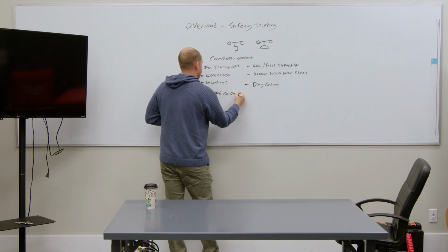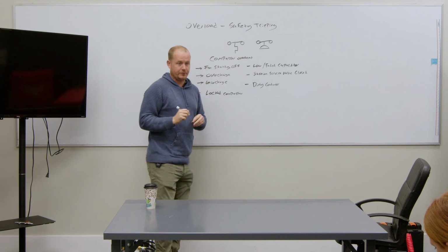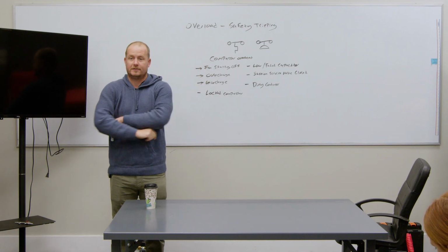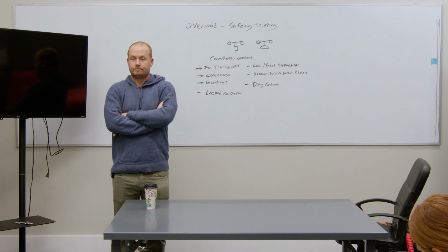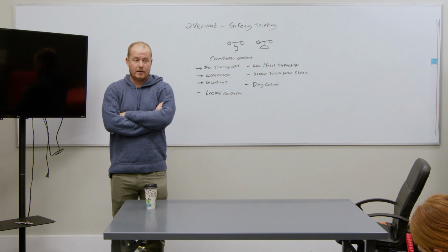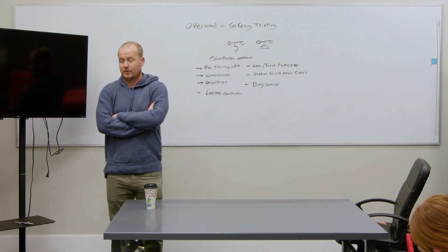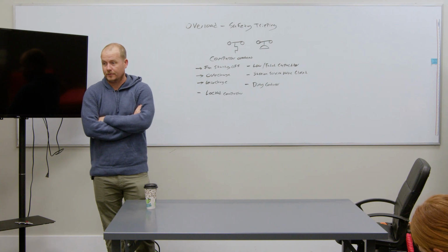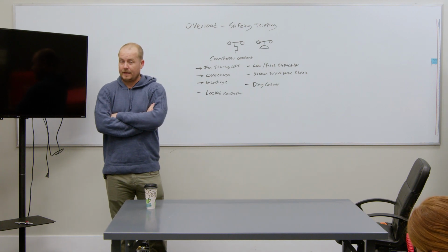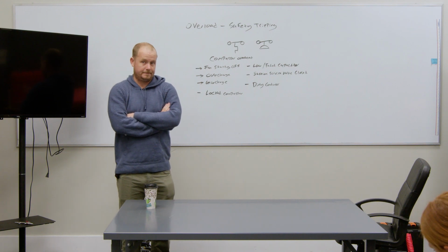But most often, why does a compressor do that? What's the most common reason on the systems we work on that a compressor does what I just described? Bad capacitor, right? Could be wiring issues too. Could be the wire going to the capacitor is burned off, or a terminal going to the compressor, the terminal lead is melted off. Could be that. But usually it's a capacitor or a wiring issue, most commonly. And then it's a mechanically locked compressor.